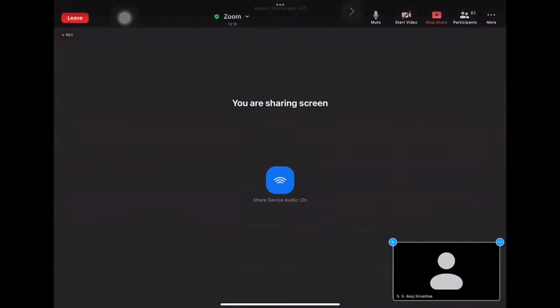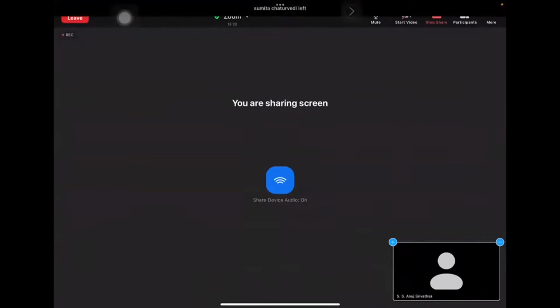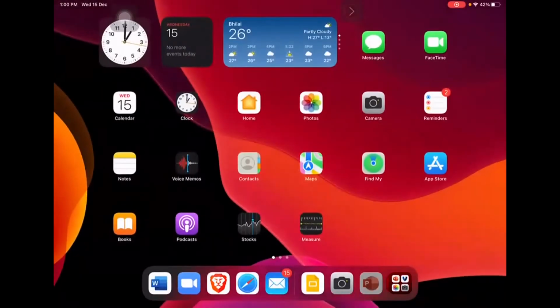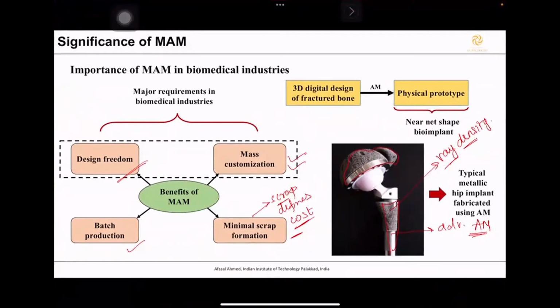Anuj, in that case, the next step which we are doing is finishing of internal cavities and holes using a die sink EDM machine. We'll generate intentional cavities like slots, circular slots, and irregular slots, and we'll use EDM milling to polish those surfaces using the same logic which I just discussed in the last presentation. Okay, sir, so there is no specific thing that is already available.